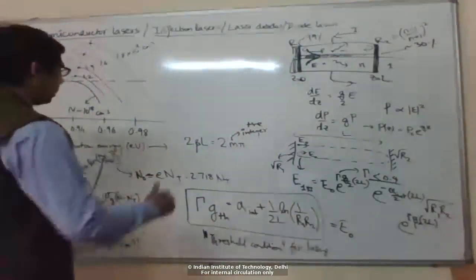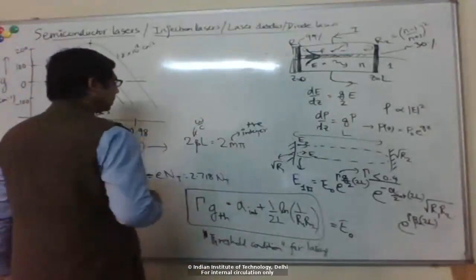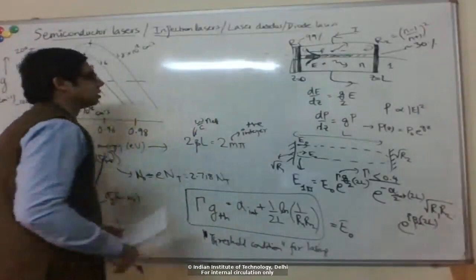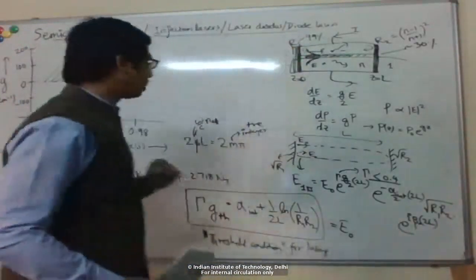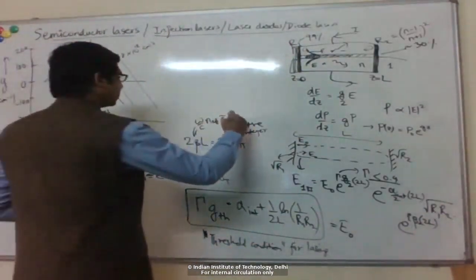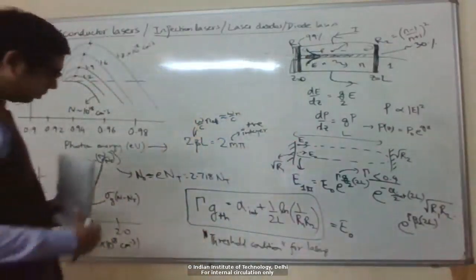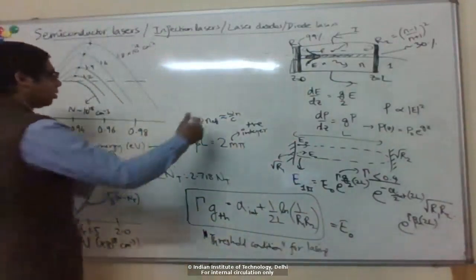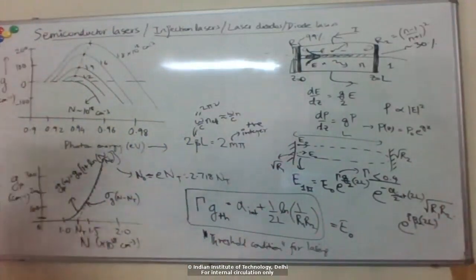Okay, so remember, we can write beta as omega over c times n effective, right? Where n effective is the effective index of the mode here, or roughly, it's basically just the index of the medium. And omega, of course, is 2 pi times the frequency in hertz.